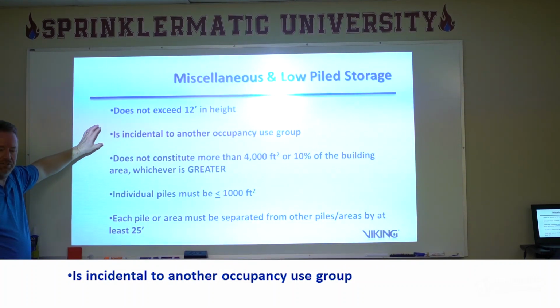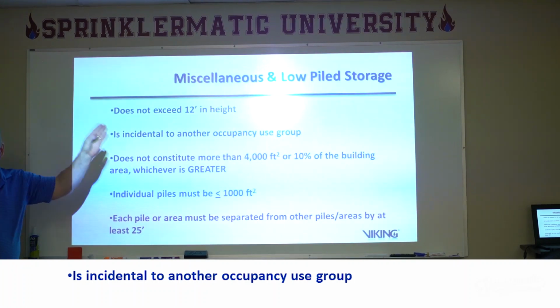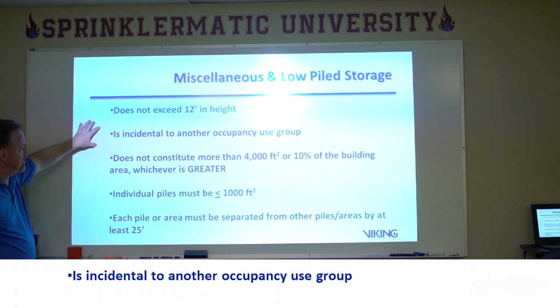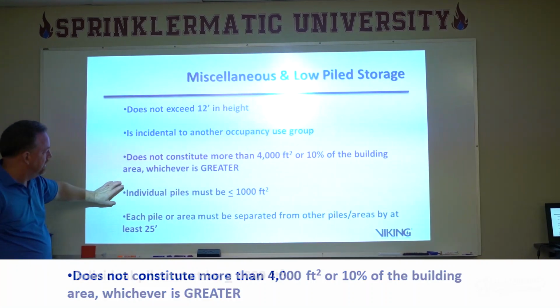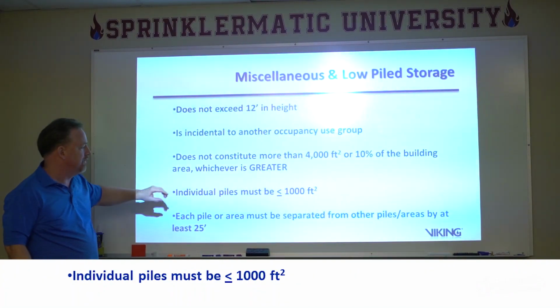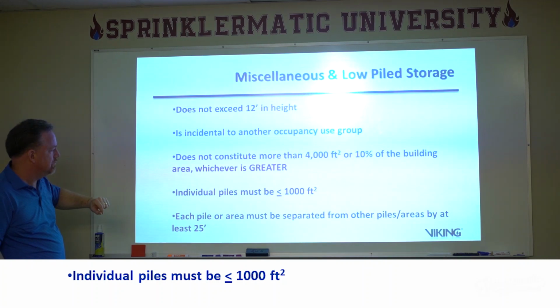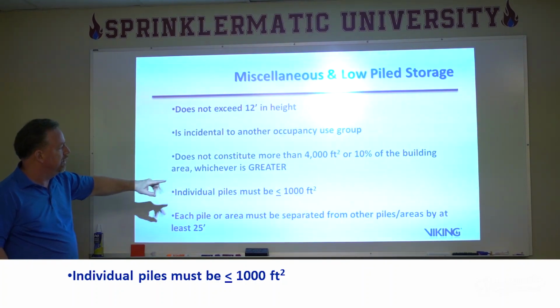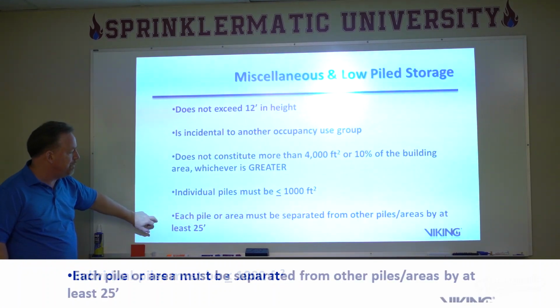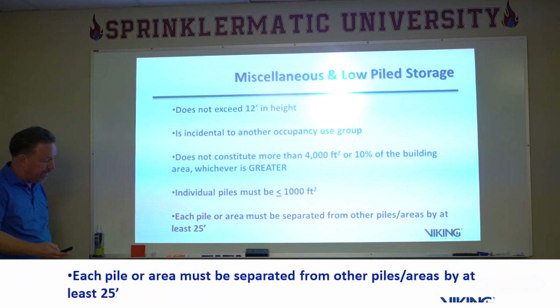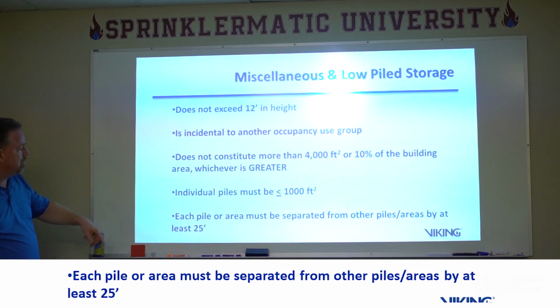In other words, it's being used a lot. There's a lot of traffic in this. It does not constitute more than 4,000 square feet in the building. Individual piles are no greater than 1,000 square feet. Okay, so this is 4,000 or 10% of the building, whichever is greater. And each pile area must be separated from the others by at least 25 feet.